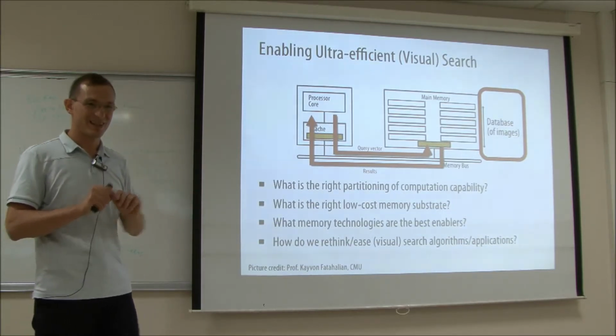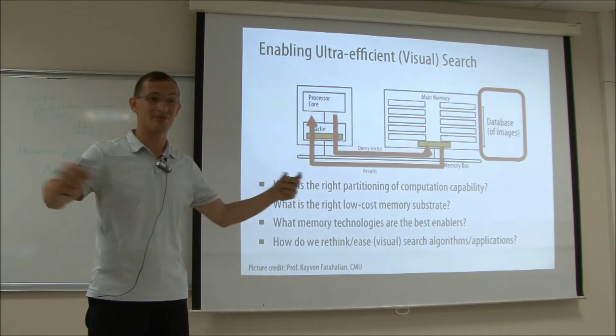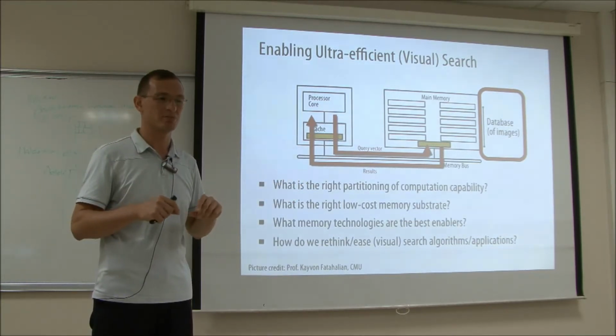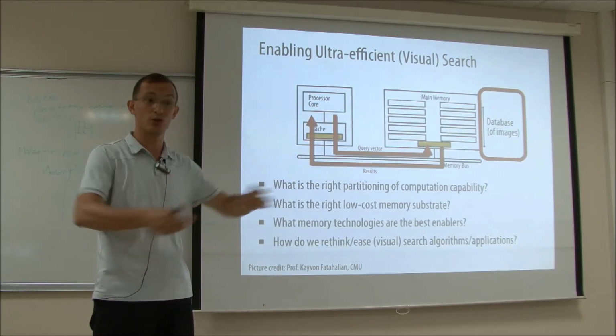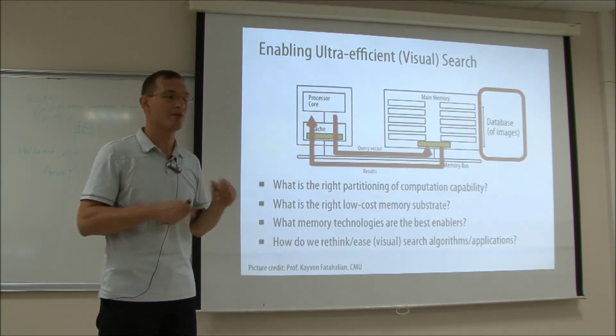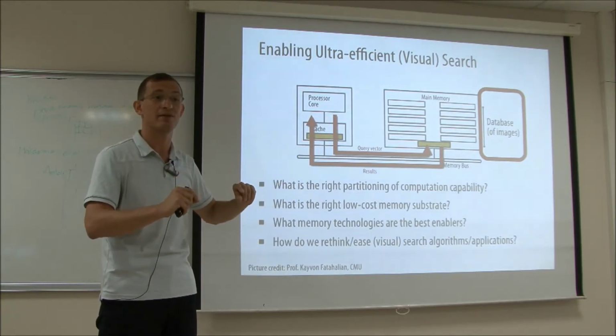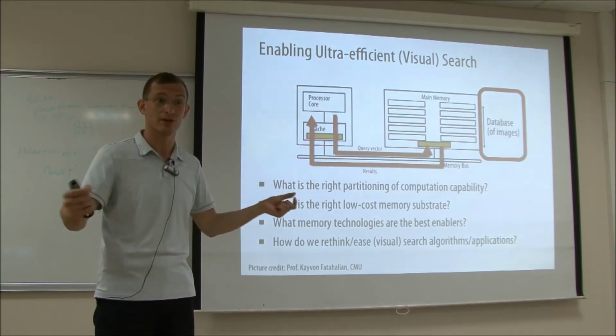I think I know what you have in mind. Something like a TCAM, for example. So we don't want to build a huge content addressable memory that's going to be very high cost. But we want to do large-scale operations. For example, RowClone does a large-scale copy. Can we do large-scale XORs or large-scale compares?